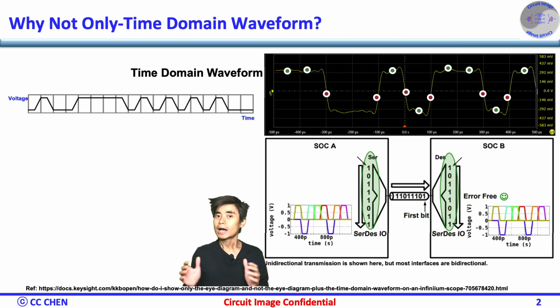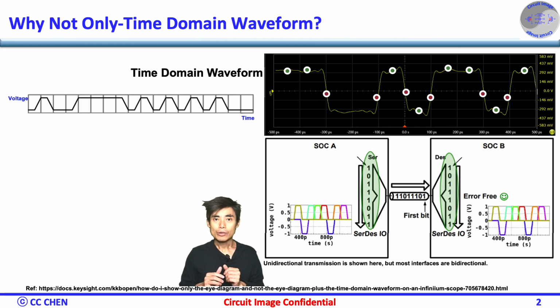Similarly, you cannot capture the timing through different edge samples in red and figure out the worst case maximum peak-to-peak jitter from so many signal transitions. To further capture the transition time in the rise and fall time, or the peaking and ringing behaviors in the waveform, visually, it's impossible. So, what can we do?